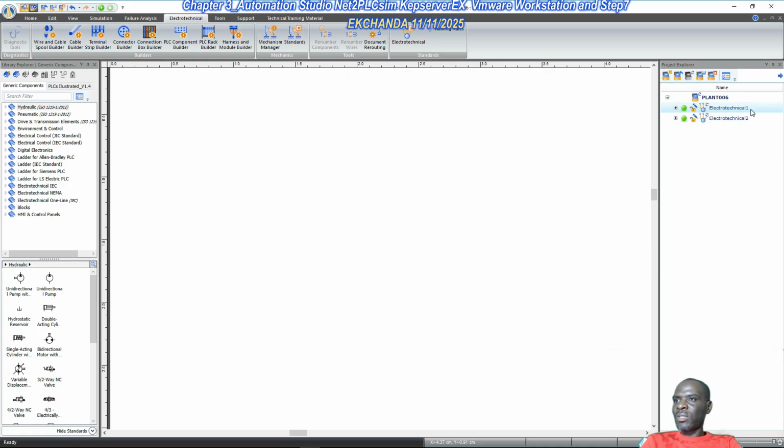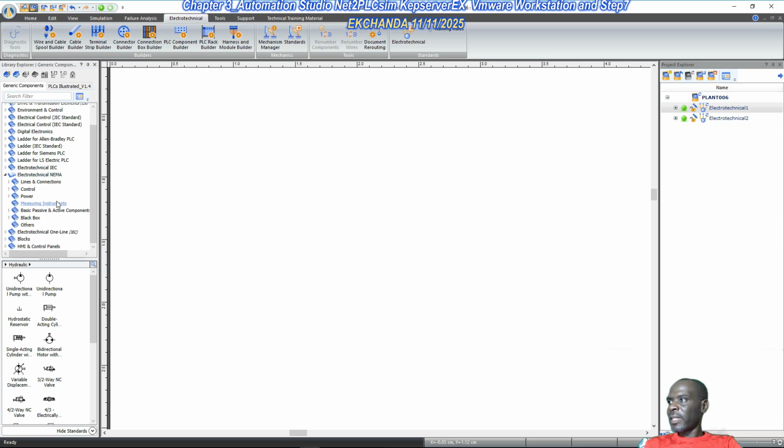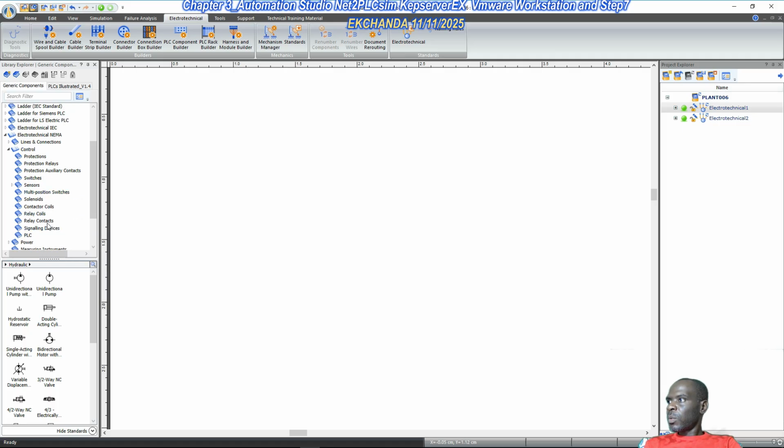I could have chosen electrotechnical NEMA or electrotechnical IEC. How do I show this to you? I'm going to go to the project library explorer, which is just the library explorer, and to where it says electrotechnical NEMA. The reason why I like using electrotechnical NEMA is because of the type of contacts. For relay contacts, I get to have them like so.